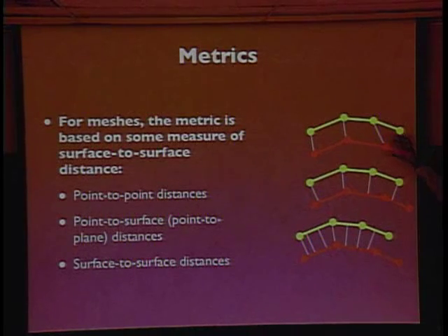Now, if these two meshes align with each other perfectly, that distance is going to be close to 0, especially if these 2 points correspond to the same thing on the object. So what we do for point-to-point distances is we simply take each point on the moving mesh, calculate its closest point distance to the fixed mesh in terms of point-to-point distance, and add those up. So the larger that thing is, the worse the alignment is. And if it's closer to 0, then they seem to align with each other perfectly. Fair enough?